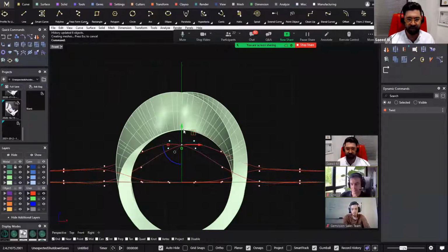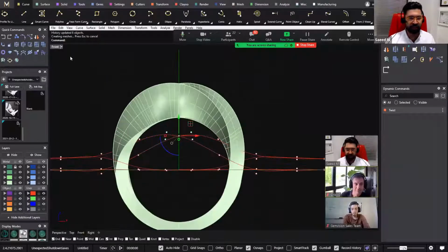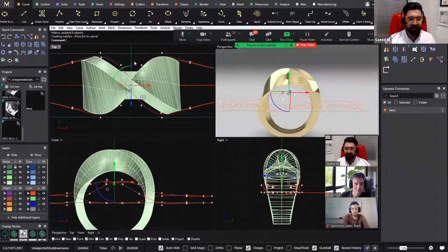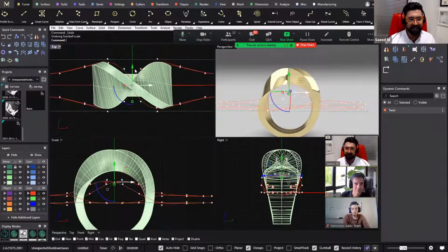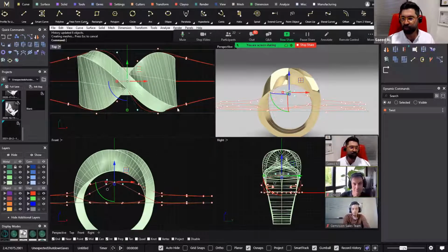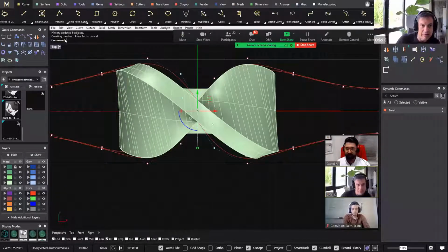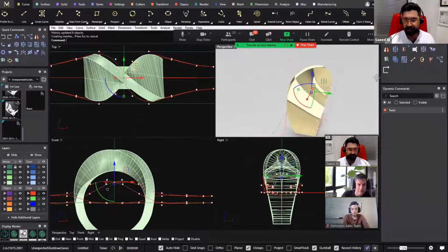Something like 4 or 5 mm. It's a fashion ring, sort of fashion ring, so it's okay. You can even do a Sculpt 1D on these 2 curves, so you will have a thicker surface on the top of the ring in case you want to put some gemstones. Yeah, with all the controls that you have, you have a lot of power to make any shape. Exactly, now you have total control on this ring.